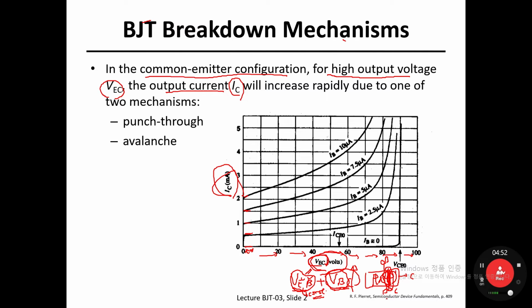Then let's go back to your PN diode theory. Under reverse bias saturation, a reverse biased PN diode can flow a very tiny amount of saturated current. However, if your reverse bias is too high, beyond the breakdown voltage, your reverse biased PN diode can flow exponentially increasing current across the PN diode.